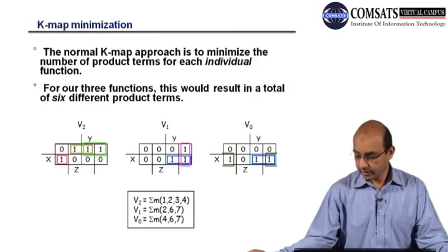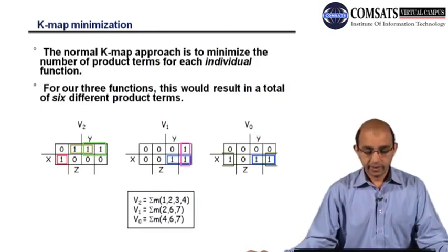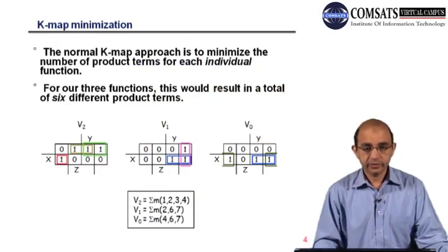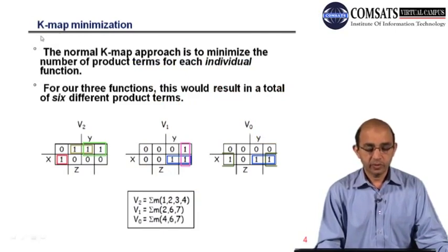If I draw a truth table, what do we need to do after the truth table? For the simplification, we normally use a K-map, because in K-map simplification or minimization we perform a predefined number of steps. We know the number of steps and the sequence.